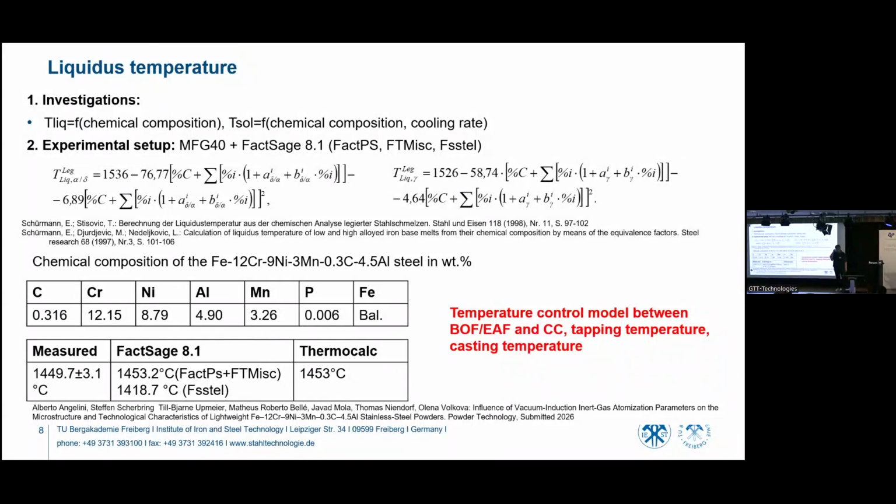We need knowledge about liquidus temperature for setting of casting temperature in the mold or in the tundish of a continuous caster, for setting of tapping temperature on BOF or on EAF. At our institute, we can measure liquidus temperature in one furnace using steel samples of about 200 gram.